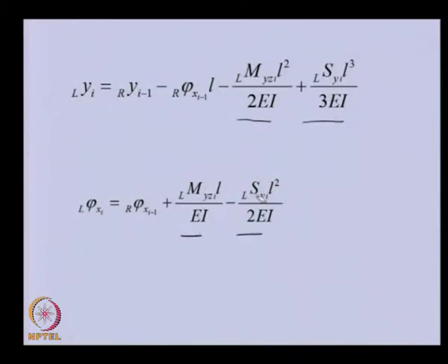This also we can get from a strength of materials book or from deflection of beam relations, these are available. So, these are the angular displacements due to shear force and bending moment. When we give a linear displacement, there is no change in the slope, because in this particular case, if we give a linear displacement like this to the shaft, there will not be any change in the slope.